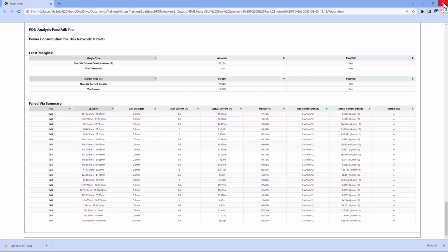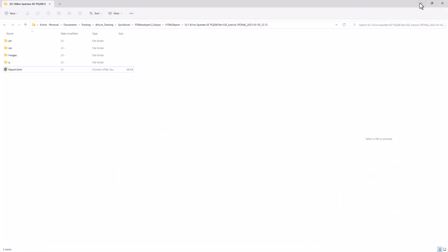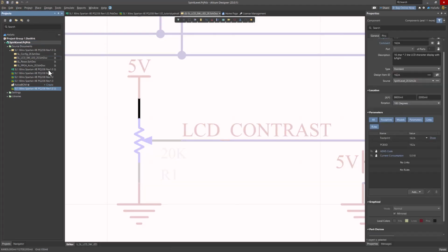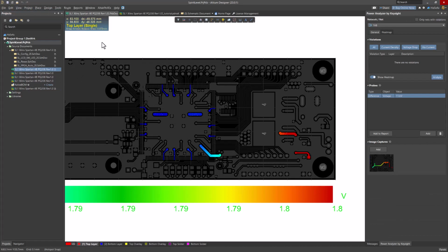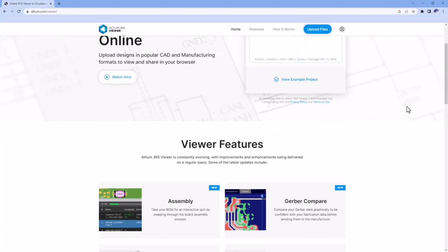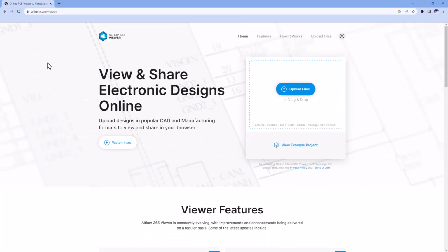It's comprehensive, it's useful for high-speed designers, and also once you're done with your design, making sure that everything has passed your test, you've updated everything, then you can go into your PCB project, export your files, like your Gerber files, your ODB++, because now you're confident in your power electronics design.